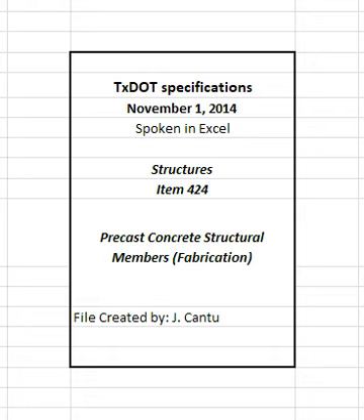4.2.1.1 External forms. Construct side and bottom forms of steel unless otherwise approved or noted on the plans. Timber forms, when permitted, must meet the requirements of Section 420.4.4, Forms. End headers may be of other material as approved. Construct forms with sufficient thickness, external bracing and stiffeners, and anchorage to withstand the forces generated during concrete placement and consolidation. Do not stabilize forms with bracing and holding devices that will remain in the finished member. Provide corners with a chamfer or radius where shown on the plans.